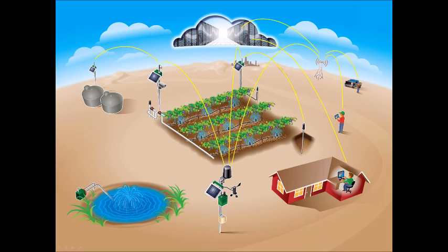Though we typically advise to design the system in the most robust way in which the base station becomes the direct point of communication. In case there's any issue communicating with this unit here, for instance, if it gets removed for service or it gets damaged somehow, you still want to be able to get the data from this far node. So it's a good idea to try and plan in the best case scenario that you can reach directly to all the units and possibly consider using more base stations to accomplish that.